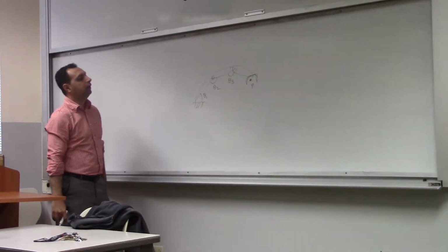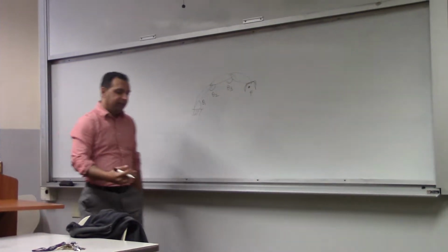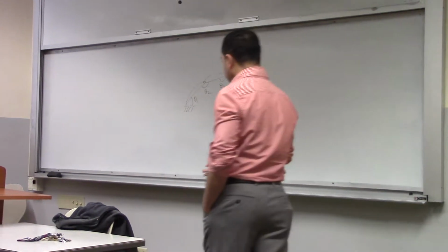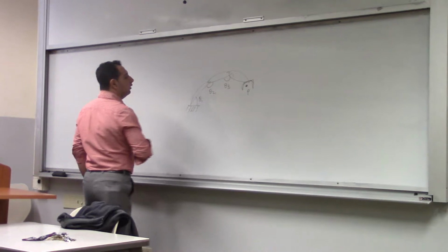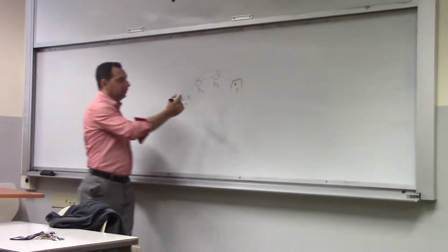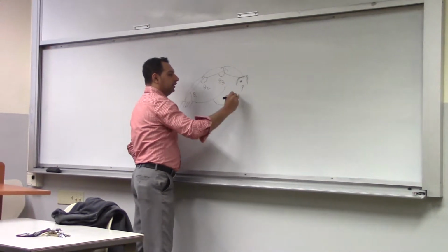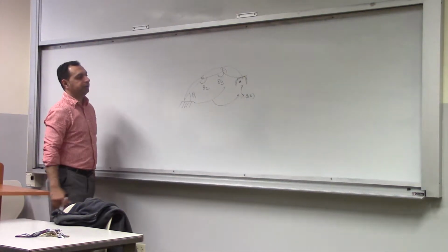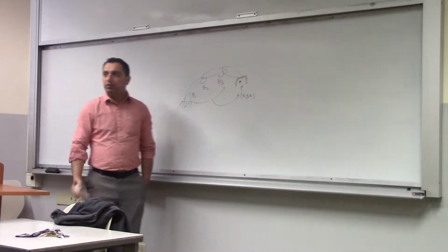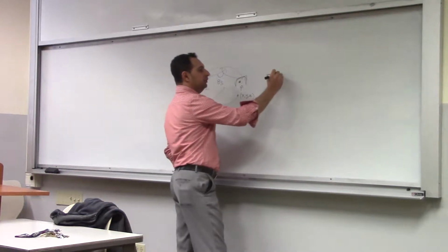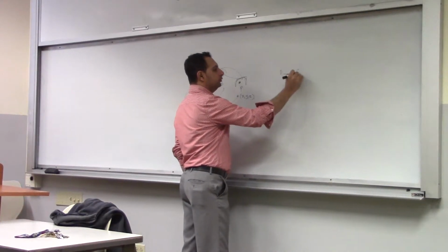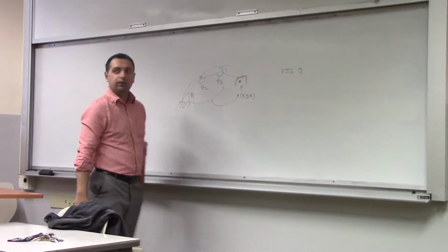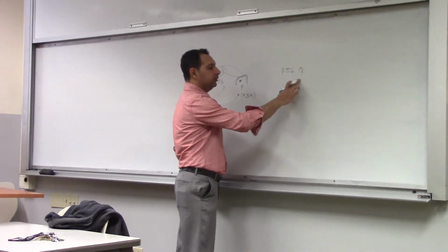That's it. Okay. Now, we did inverse and forward kinematics, so we know how these values relate to the x, y, and z, and also the orientation. We did this with forward and inverse kinematics, which is the relation between P and Q, back and forth, right? P is the point in three-dimensional space, and Q is your joint angle.